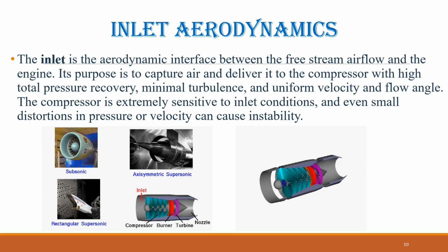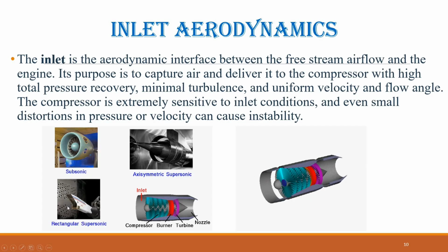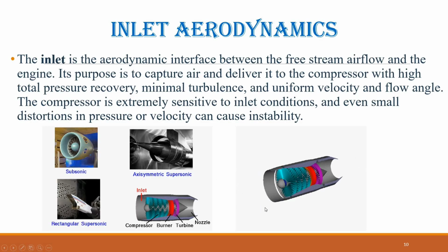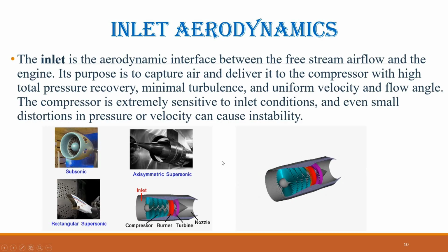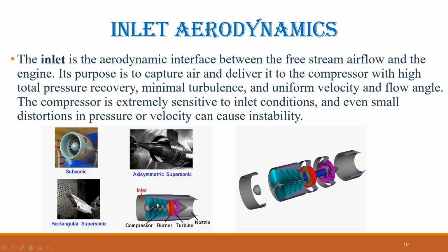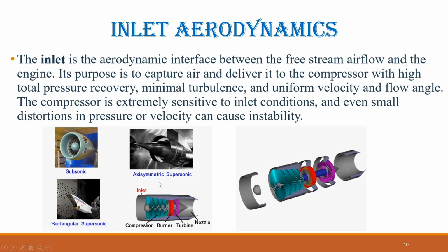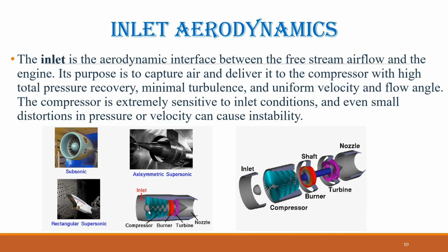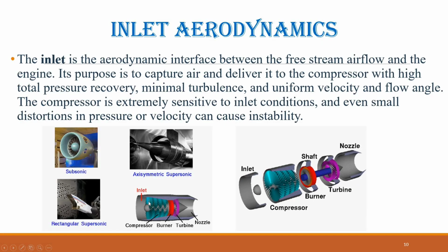Inlet aerodynamics. The inlet is the aerodynamic interface between the free stream airflow and the engine. Its purpose is to capture air and deliver it to the compressor with high total pressure recovery, minimal turbulence, and uniform velocity and flow angle. The compressor is extremely sensitive to inlet conditions, and even small distortions in pressure or velocity can cause instability.